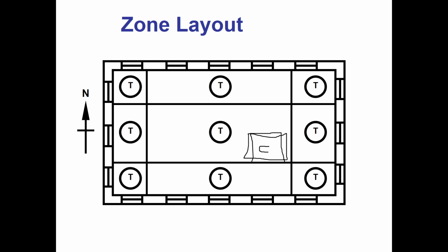The VAV boxes have multiple steps to balancing them. For starters, I have to calibrate the sensors on the VAV boxes. We haven't gotten to that point yet, but we will. The VAV boxes have inlet sensors on them to measure pressures and calculate the CFM. So the VAV box knows at all times how much CFM is running through it. And those sensors need to be calibrated. So usually it's the air balancer and the controls guy working together to do that.